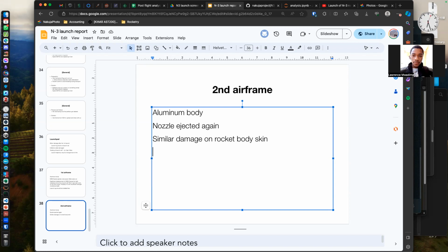So a suggestion was having 2 bolts below the nozzle, maybe 2 or 4, maybe 6, rigidly holding the nozzle in place, such that even if the bolts holding the nozzle to the casing or the airframe fail, we still have something retaining the nozzle within the airframe. Maybe that can be checked out for the future.